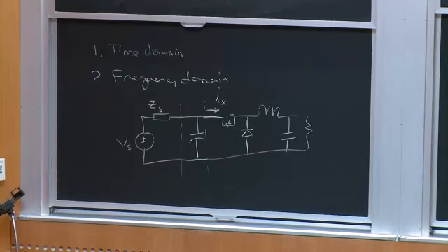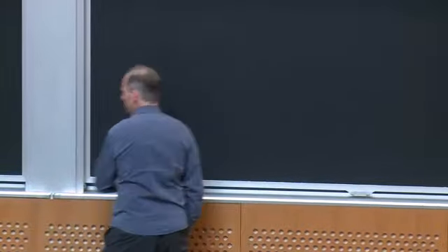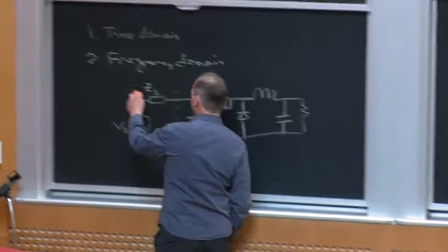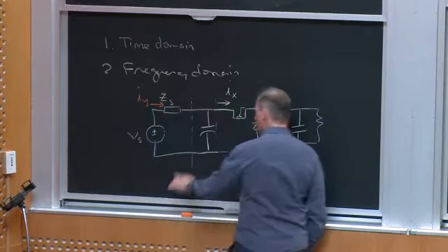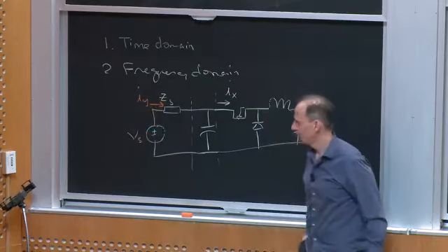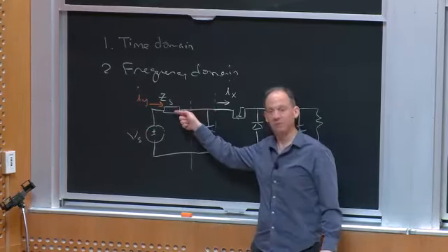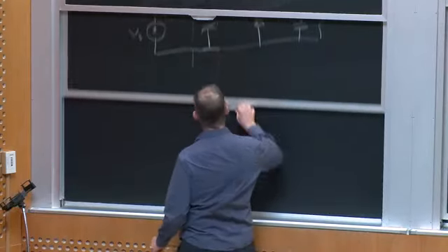What would be a model for this as far as conducting noise into the input? And maybe I would consider my noise to be whatever ripple here is, I'll call this Iy, right? So if I'm driving ripple current back into this input, then I'm generating noise in the input, and maybe that's what's interfering with my radio, okay? So how would I model this?